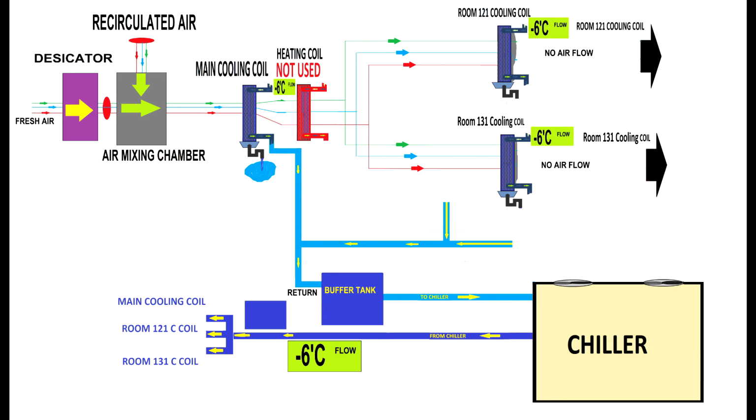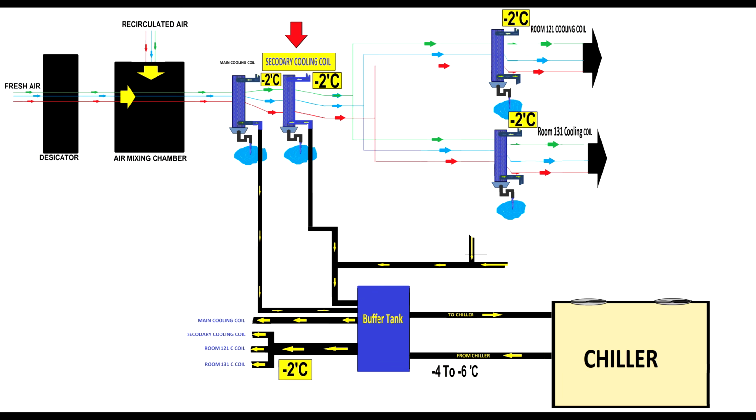Also here you can see an incorrect system. It's a little bit hard to explain. I will do another video specific for this one to explain. This is an incorrect design. Some people thought if they use a desiccator to run very low moisture into the air, they will avoid the icing-up phenomenon on a heat exchanger that runs on minus 15 degrees glycol, minus 6 degrees glycol, sorry.